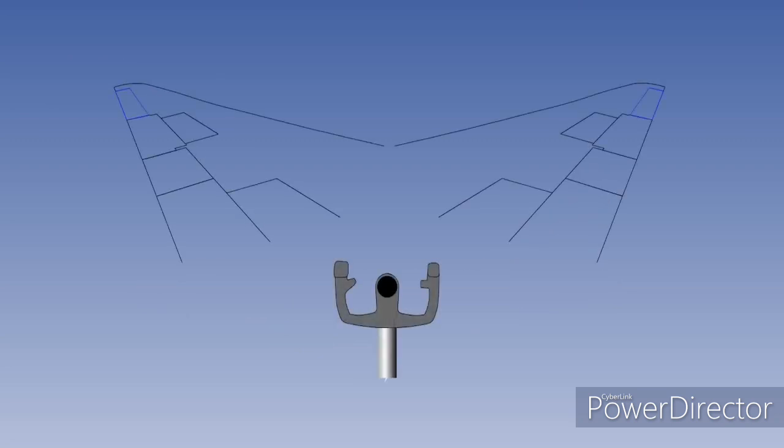Smaller aircraft use ailerons for control in roll, but the majority of modern high-speed jet transport aircraft use a combination of ailerons and spoilers. You may consider this a strange-looking aeroplane, but the two halves of the wing and the cockpit control have been displayed this way to give as large a view as possible. Also, the aileron displacement shown in the following illustrations is emphasized for clarity and is much bigger than that required in practice.